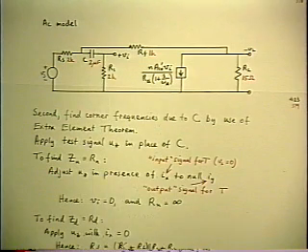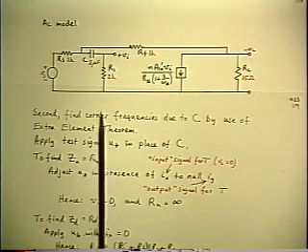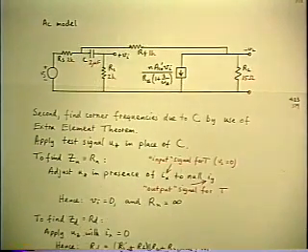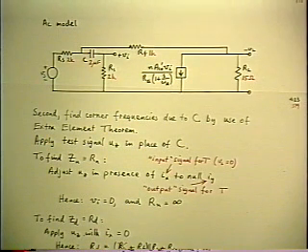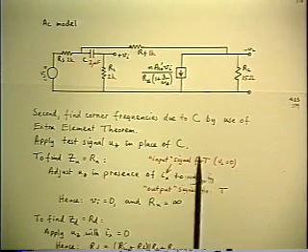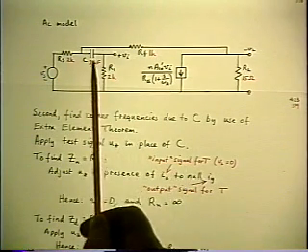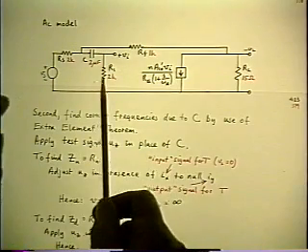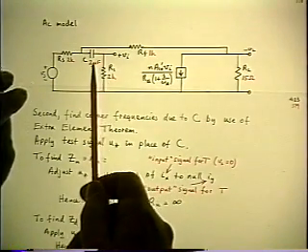The Rn is irrelevant. You can see that right off, because the C is a coupling capacitor in series with the signal path around the loop, just like the coupling capacitor was in the common emitter amplifier stage. So we know there is not going to be a zero resulting from the capacitor. But we can verify that by actually applying the theorem and calculating Rn.